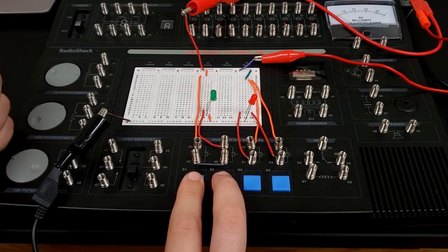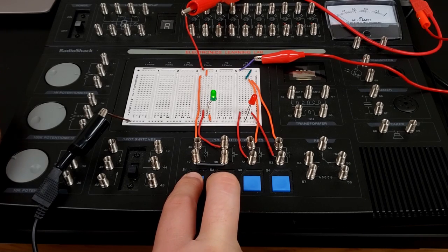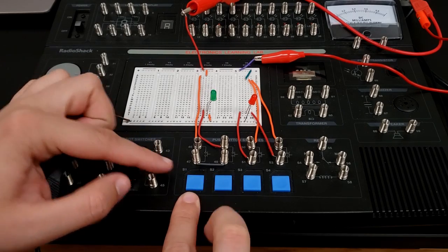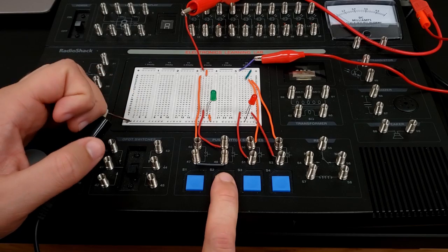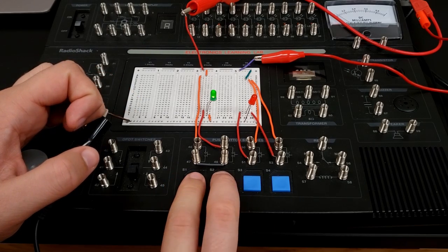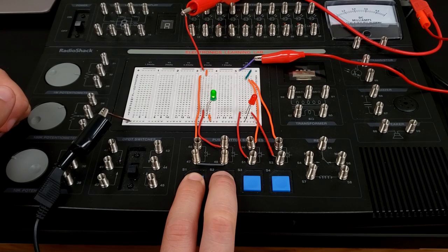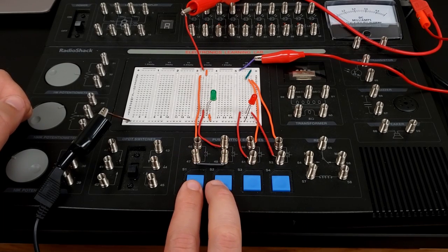Now if I press both of them, so we have our 1, 1 input, that LED now lights up, and so we have a 1 output. This means this is our AND gate, because 0, 0, 1, 0, and 0, 1 all give us 0 for the output, and 1, 1 gives us 1 for the output. So that's your truth table and the circuit demonstration for the first circuit of part A.